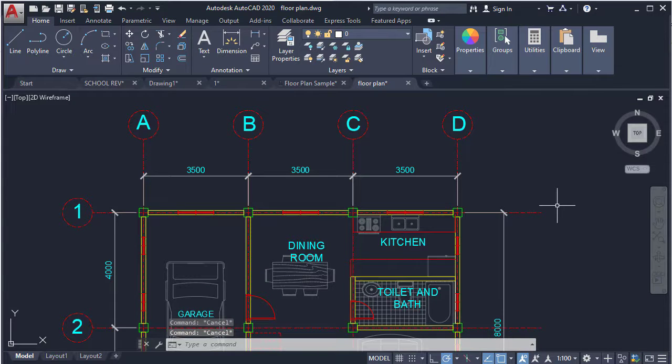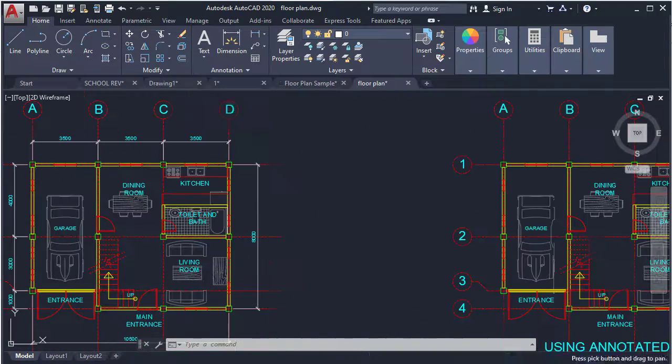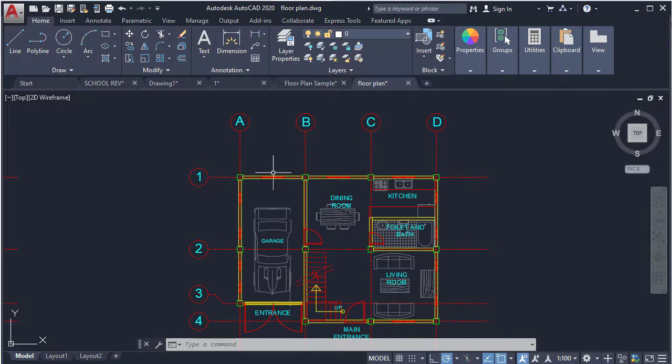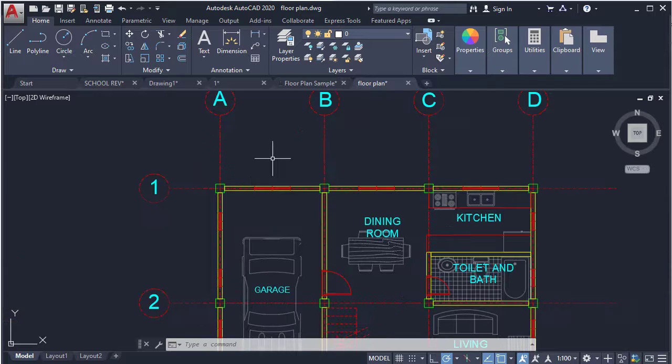If your drawing plan is composed of different scales, you need to create different dimension styles for each of those scale drawings. For example, for a scale of 1:100, you need to create a dimension style for 1:100, and a separate dimension style for, let's say, 1:10. An alternative to that is to use annotative scaling. Under annotative scaling, you don't have to create additional dimension styles because only a single dimension style will be used for different scales of drawings.